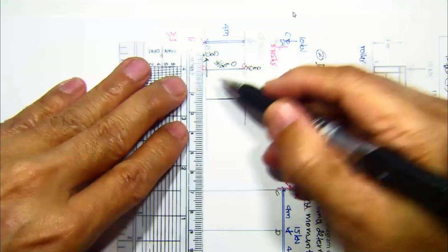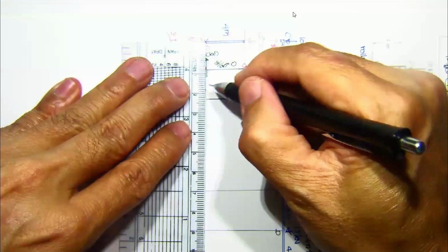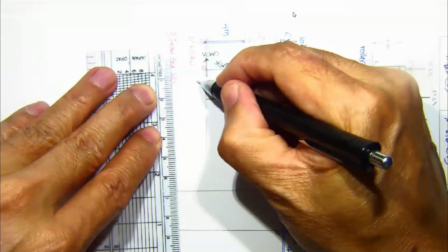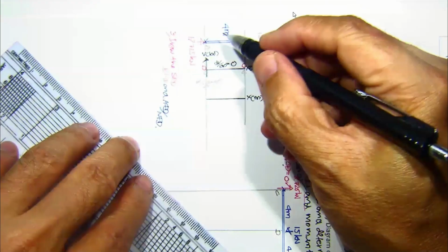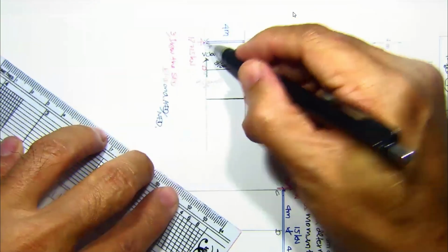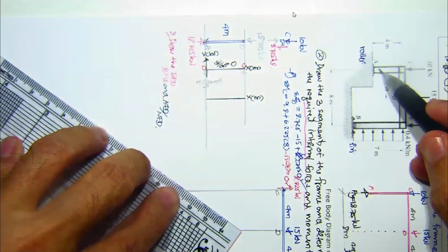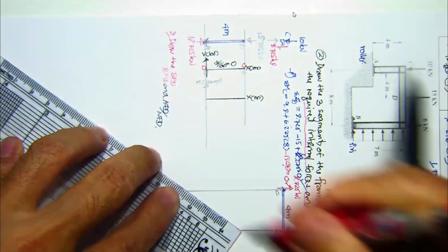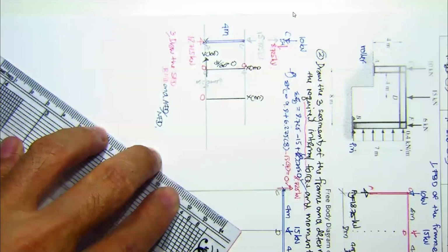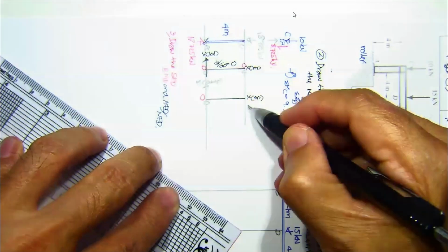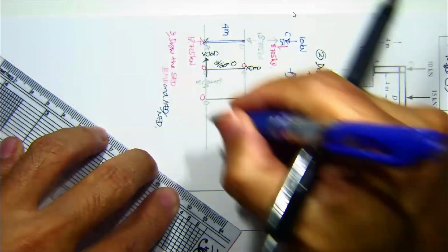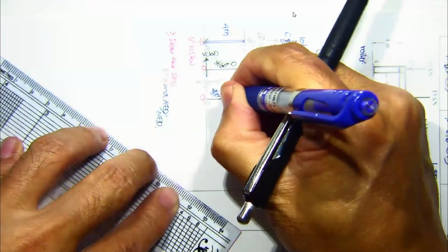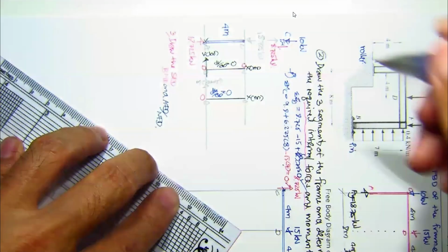diagram and follow what we have over here. We put this one M in kilonewton meter. This is a roller and no external moment. So the moment over here is going to start from 0, and then the shear is 0. So we have dM by dx equal to 0.